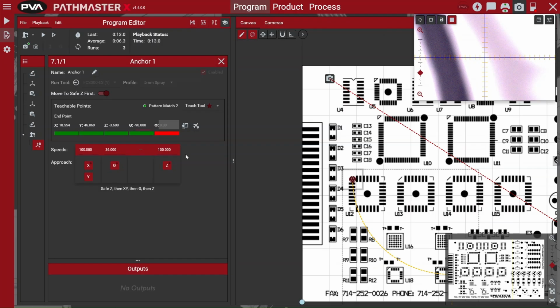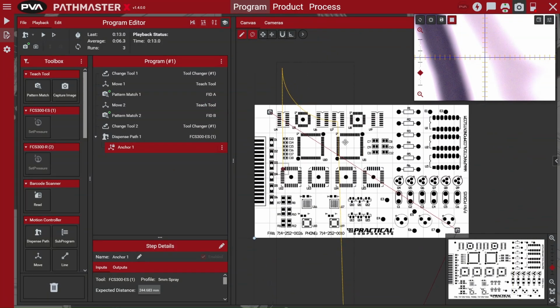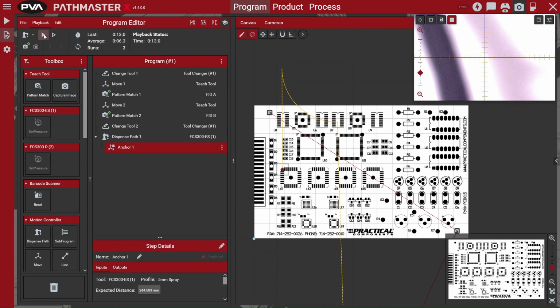The coordinates are edited to give a specific theta and phi position for the anchor step. The approach vector is automatically updated and places the phi in the sequence before the z move. It is not advised to place the phi with other axes, as it cannot participate in coordinated motion. A warning is displayed that indicates that phi will not perform coordinated motion. If phi is left in a lane with another axis, phi will always move first.